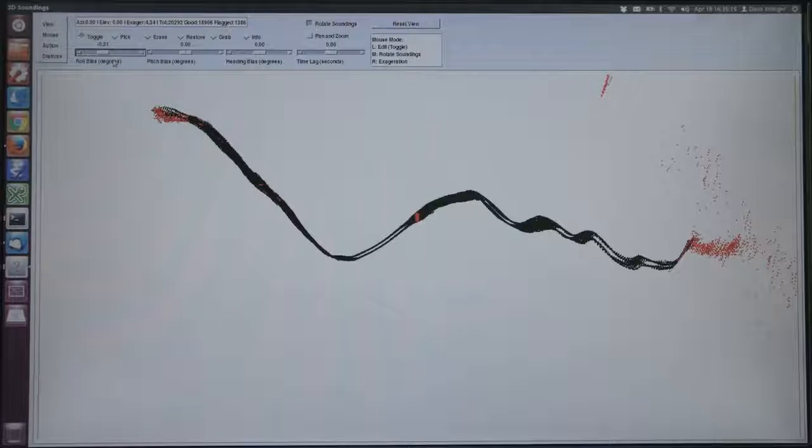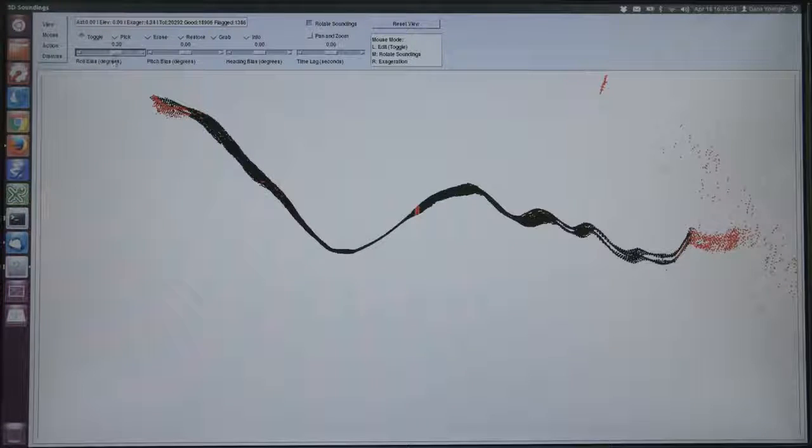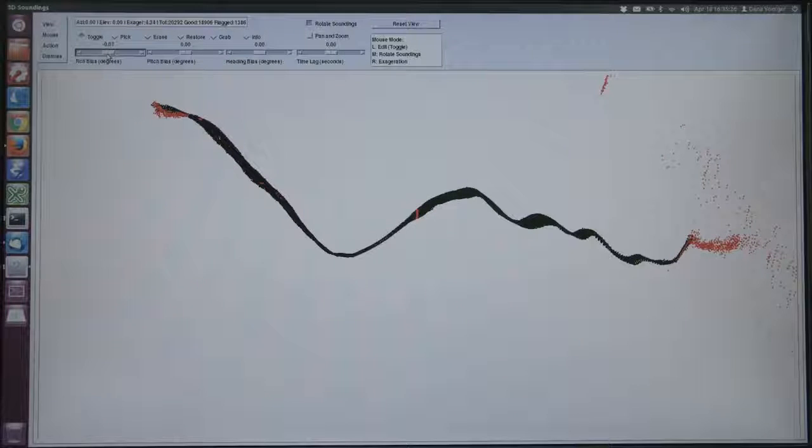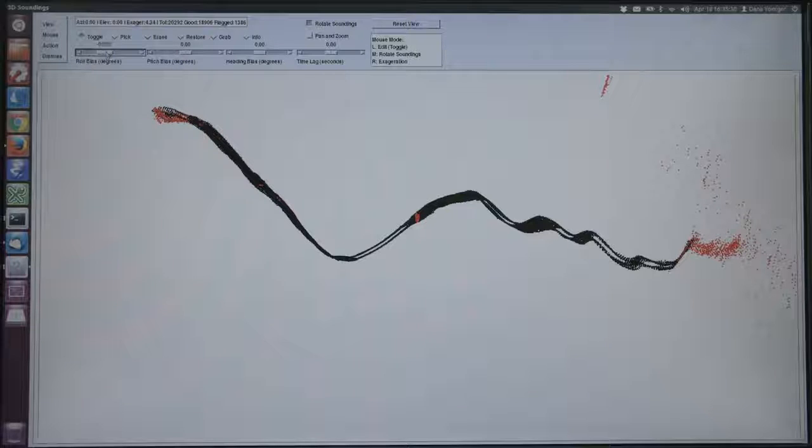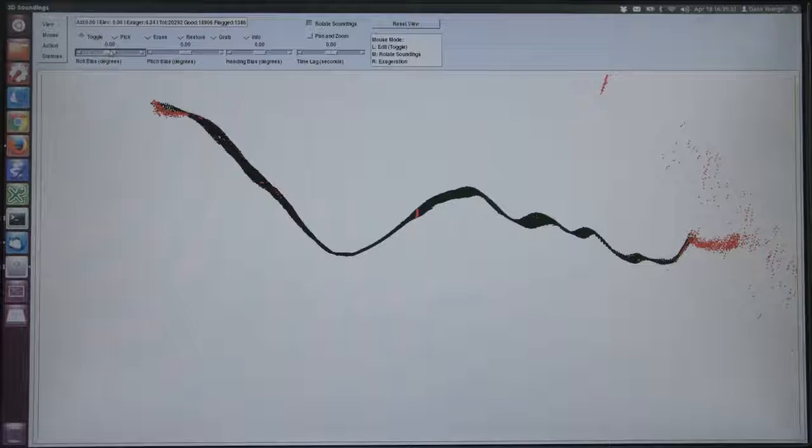So basically what I do is I find the roll bias that gives me the maximum agreement between these two, and that's actually the roll bias that I like. So right there happens to be 0, okay? So I guess the guys really lined the sonar up right when they put it together. Actually, we can't really distinguish, well, maybe a 1/10 of a degree or so here. But anyway, this is a way of manually twiddling the roll bias.